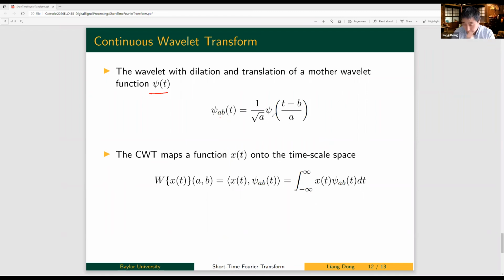And it itself is a small wave. Let's say I'm using this wavelet. You can think that you multiply this wavelet with your x(t), which is also a windowed signal. Indeed, you are windowed by the boundary of your small wave. It's windowed. Now, if you dilate that, you extend that.